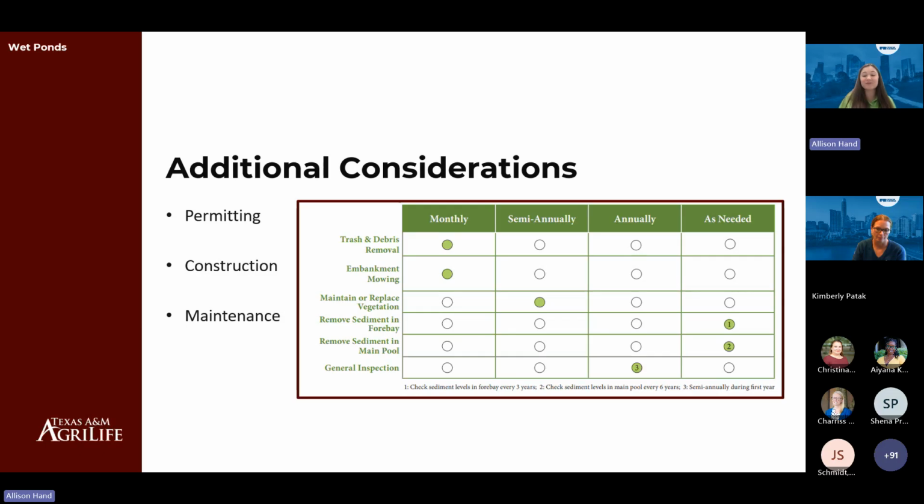Just generally saying every few years or as needed is not as helpful to your maintenance team as saying every 3 years, check this, or after a storm of at least 3 inches of rainfall, check these items. And for those in a coastal area, you may have a shallow water table, tidal influence, or high salinity levels on your site. The design set provides considerations to adapt your design to be more resilient and still effective under these conditions.